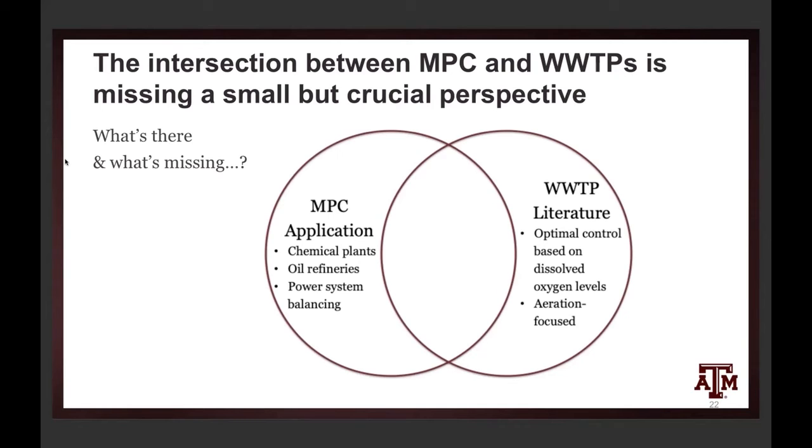A big portion of the energy used in wastewater treatment plants goes to aerating the sewage, about between 30 and 40% of the energy in a plant. And thus, a lot of the research out there currently focuses on optimizing for dissolved oxygen levels, so it's more aeration focused. So there's a clear intersection between these two things that's missing, and that's what we're trying to focus on with my research.